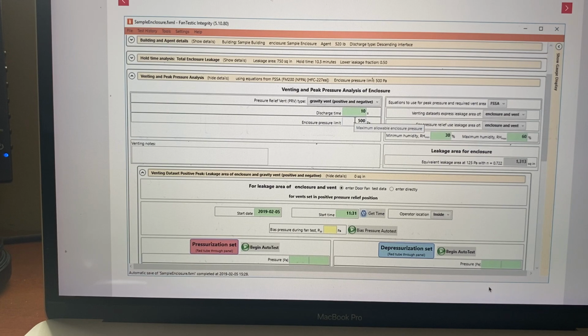The enclosure pressure limit, that's just the maximum pressure the enclosure can withstand without damage. 500 pascals is the default. This can be changed if you have data to prove that the enclosure could withstand more. And it's going to be based off the weakest point of the enclosure. So 500 pascals is a pretty safe limit for almost any enclosure. A lot of enclosures can take up to 1,000, but ideally you would have some kind of...